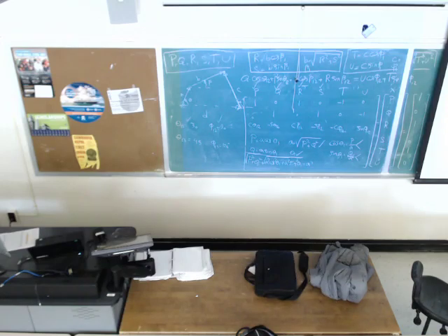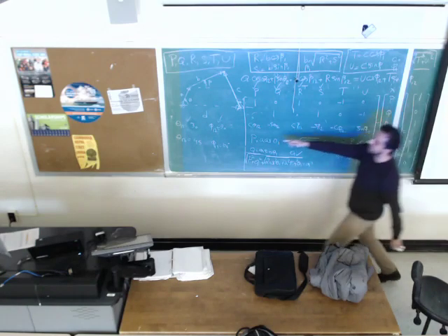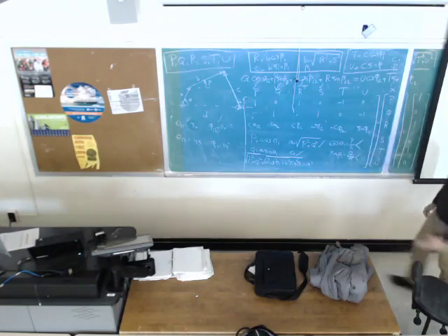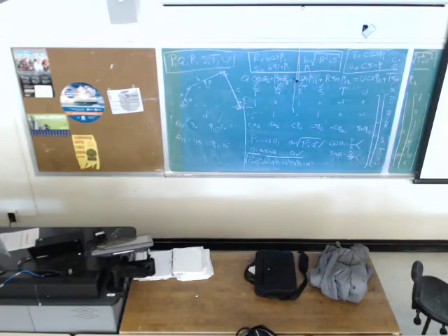What I ask you to do, I think on the homework, is what if I ask you to design to generate this desired function, and we would like to have a crank rocker? You got these values. Is it a crank rocker? First, you should check if it's a Grashof mechanism. Shortest link is 0.431. Longest link is 1.42.